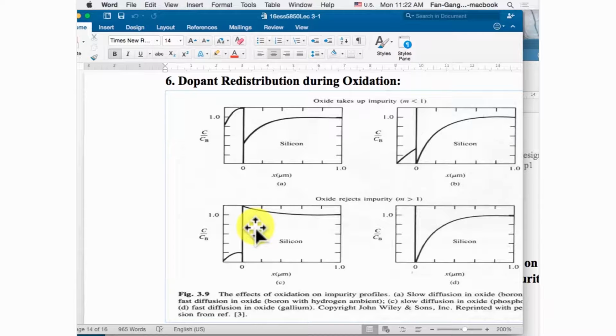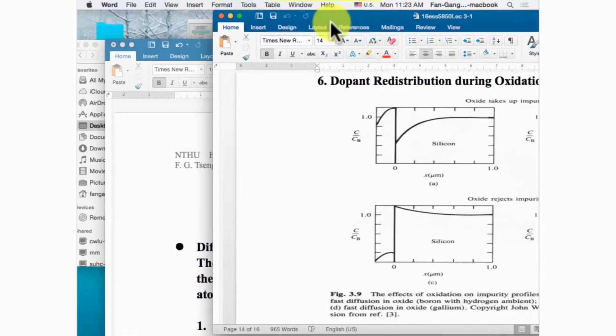That may be okay, because sometimes if you have a high concentration, you just increase the current rate and you won't get some defect phenomena. It might be okay. But if you have too much dopant piled up, it may cause channel shortening. Maybe you have some different problem. Okay, so that's a real situation.